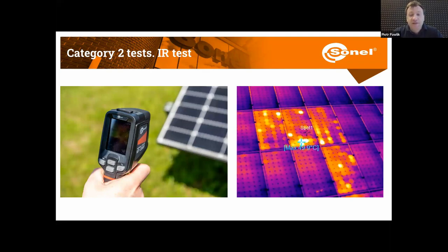The second type of the test is the module hotspots. Module temperature should be uniform with no areas of significant temperature differences. A hotspot usually indicates an electrical problem. Here we have a very nice picture which shows some electrical problems. Probably here the panels should be replaced.